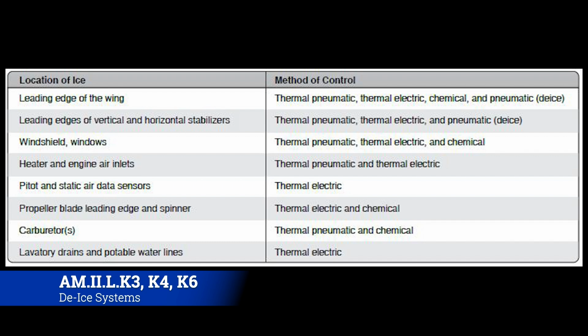The reason being is that the pneumatics would change the geometry of the fan cowl, and thus kind of defeat the point of the fan cowl. And with chemical, you don't want to introduce that into a running engine, which would not be good for anything. So you're kind of limited to the ways that you can de-ice an engine. Pitot heat and static air data sensors are thermoelectric. That's pretty much universal. I've never seen any other way to do that.